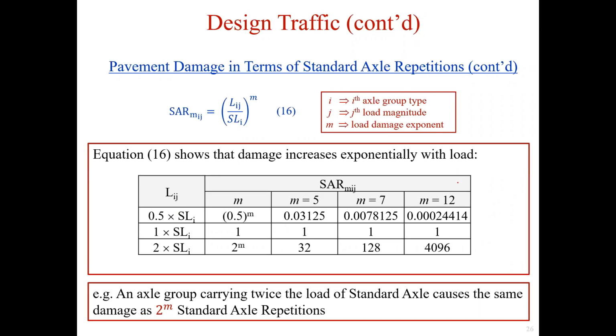From equation 16, we can see that damage increases exponentially with load. For example, an axle carrying twice the load of the standard axle causes the same damage as 2 to the power of M standard axle repetitions, as shown here.